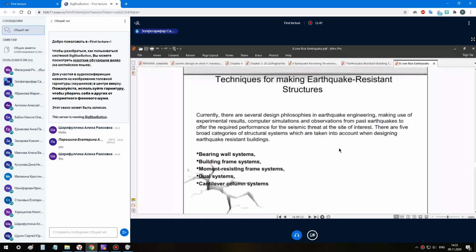Another way is using a braced frame system for building construction of structural steel and concrete. Lateral resistance is provided either by diagonal steel members that extend between the beams and columns to provide horizontal rigidity, or by concrete masonry or load-bearing shear walls that provide lateral resistance but do not carry the structural weight.